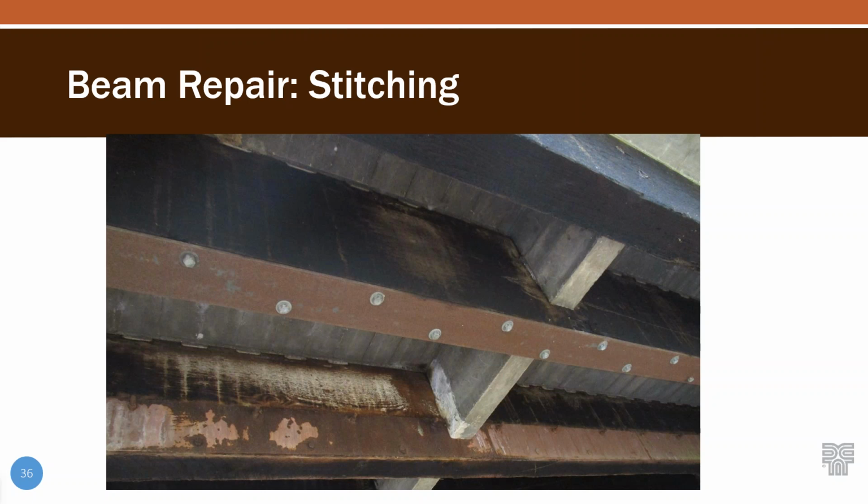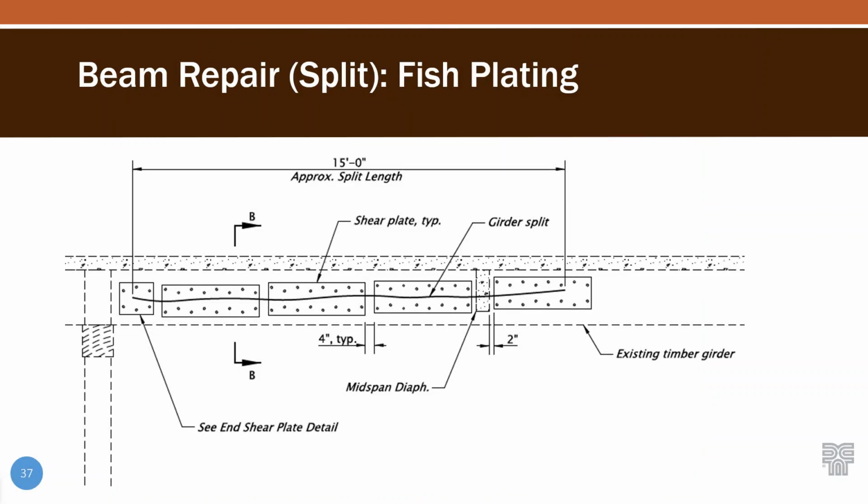This is what it looks like in practice. You can see the lag bolts running up the member and then that steel plate along the bottom. I will say that it has a great service record. I see a lot of these repairs in the field as part of the inspection and just seeing inventory. I personally haven't been able to run through the calcs on it and get them to quite work. The weak link is the lag bolt on these. But again, that's a repair that's out there that I see.